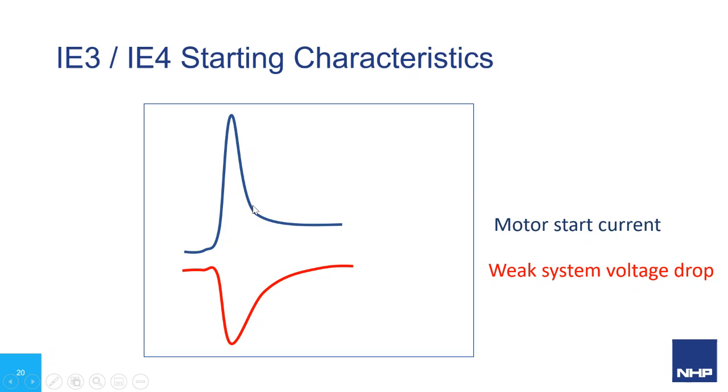If we have a weak supply, this affects the applied voltage in the system, the standing voltage in the system. In a weak system, that voltage will drop away. If the voltage drops away, the coil has a tendency to de-energize, or to try to de-energize, with less magnetic force, and of course that's going to lessen the contact force.